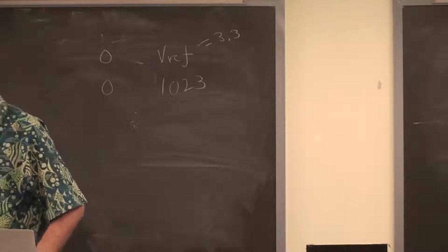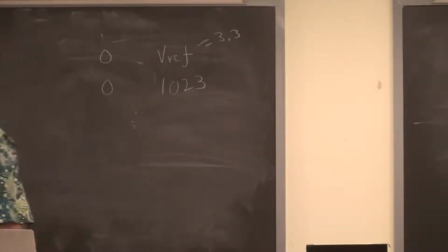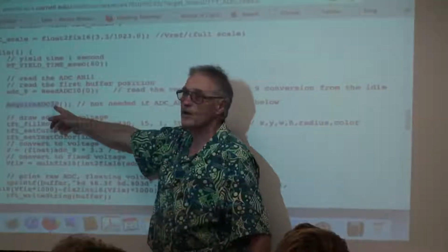But you're delaying for 60 milliseconds in between each of these threads. Won't the capacitor have leaked out at all this voltage at that point? The acquire starts the conversion, which finishes a microsecond later and stores the value in buffer 0, which is then read 60 milliseconds later. So the conversion is long done. Okay, so the acquire is not the hold. The acquire is the hold and the conversion. The acquire starts the hold and conversion, both, yes. Everything is phase locked off of the acquire.